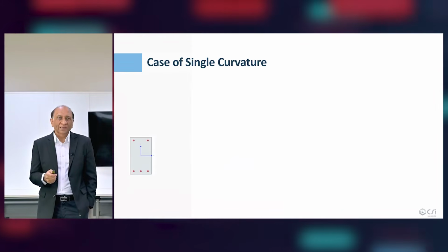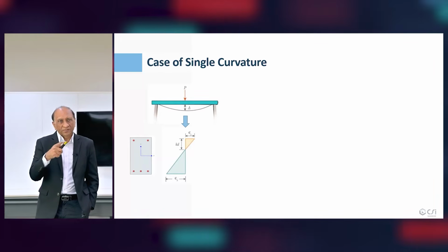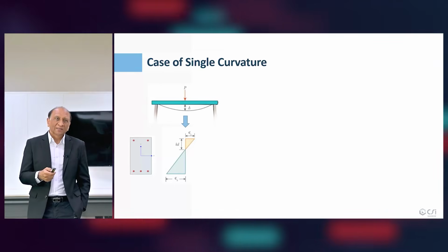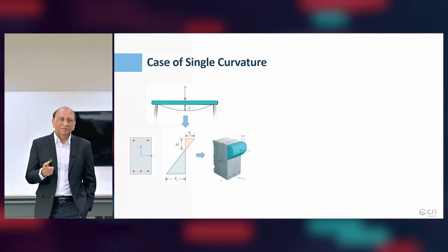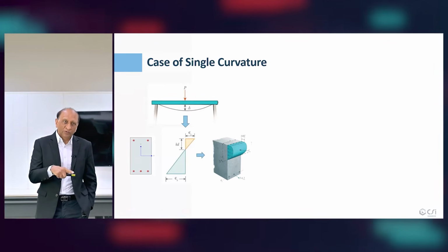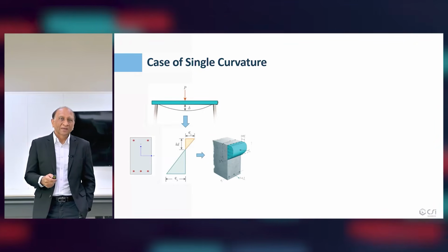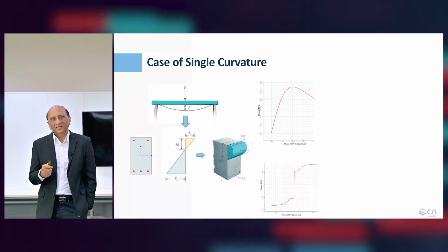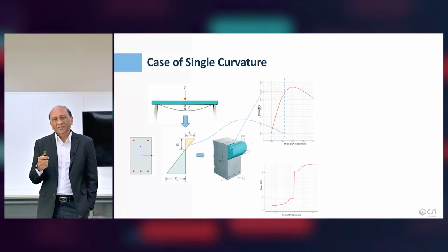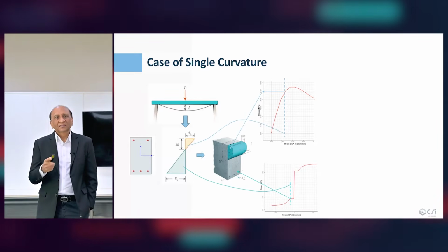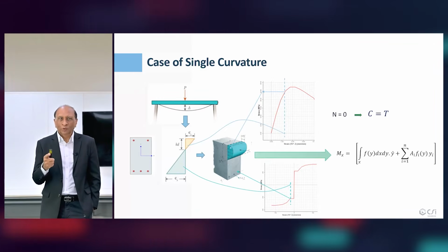We can repeat the same thing for a beam under curvature. Let's say it is under bending, and then it is curvature. So it basically has a non-uniform strain, and we have a curvature. In this one, same thing, the curvature will produce concrete stresses in some portion and zero stresses on the other, or small negative tensile stresses, and stresses in steel. And using the same concept, we can extend the same way. We can look at the strain for 0.003 and then the corresponding stress, and the same for the steel, and then we can assume that this is an equilibrium, no axial load.